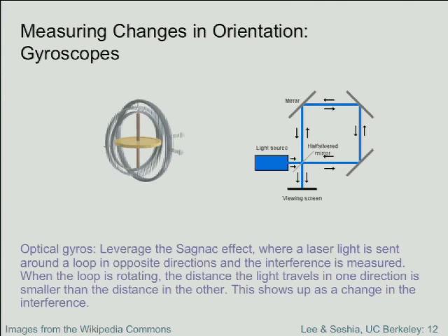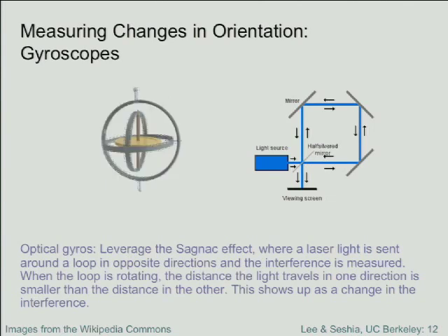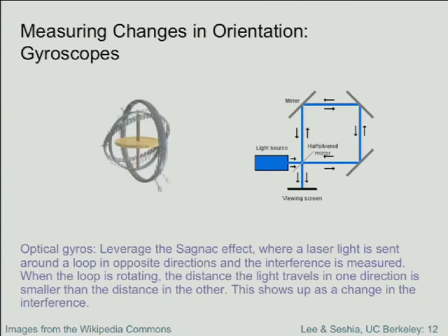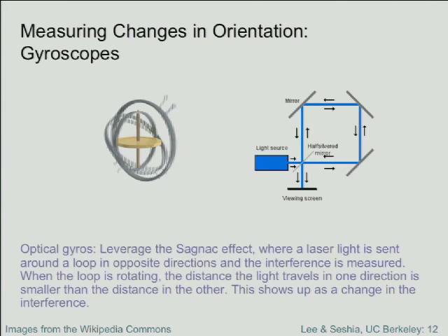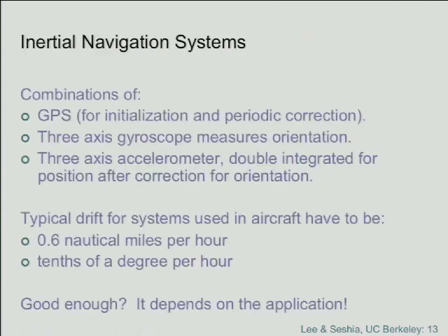Inertial navigation systems, these are the things that tell an airplane where it is. These actually use a combination of techniques. A lot of people assume that they just use GPS. GPS is not reliable enough for aircraft. Okay? So they have actually rather elaborate systems that use a combination of gyros, accelerometers, and GPS. And they can actually keep pretty accurate track of where they are, even if GPS drops out for several hours. But what they do is they use GPS to periodically reset it to a known good point. And then they use the onboard accelerometers and gyroscopes to figure it out from that.